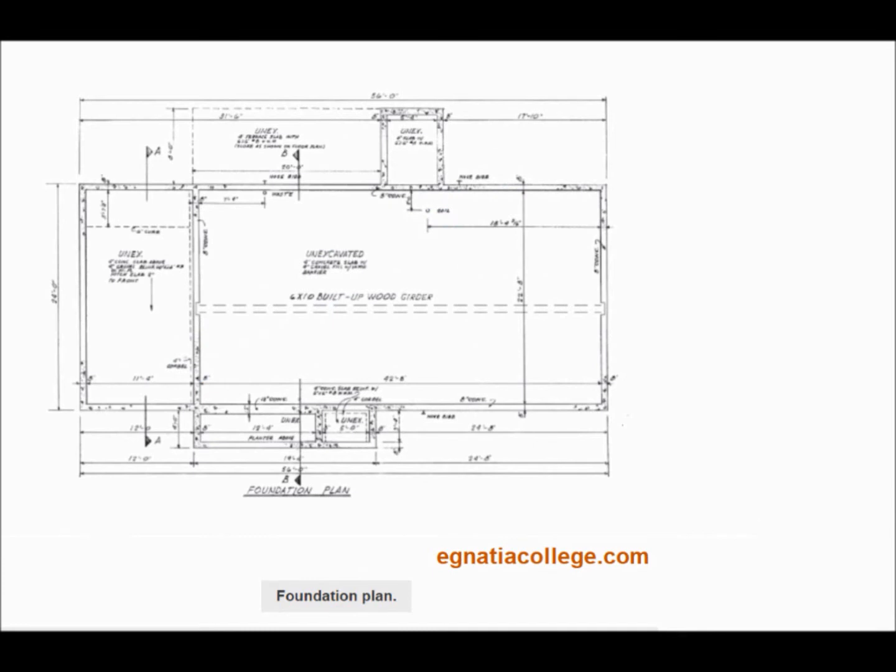The foundation plan includes all the dimensions necessary to lay out the footings and foundation walls. The footings follow the walls and may be shown on the plan. If they are shown, it is usually by means of hidden lines to show their outline only. In addition to the layout of the foundation walls, dimensions are given for opening windows, doors, and ventilators. Notes on the plan indicate areas that are not to be excavated, concrete slab floors, and other important information about the foundation. Floor plans.